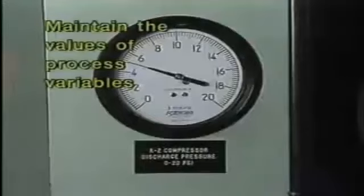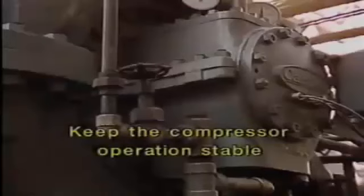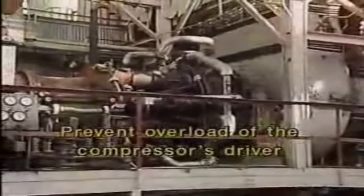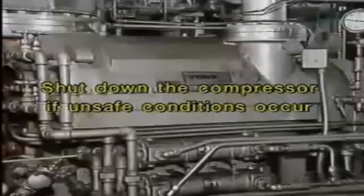They provide information about the compressor's operating conditions. They maintain the values of process variables, such as the compressor's discharge pressure. They keep the compressor operation stable. They prevent overload of the compressor's driver. And they can shut down the compressor if unsafe conditions occur.